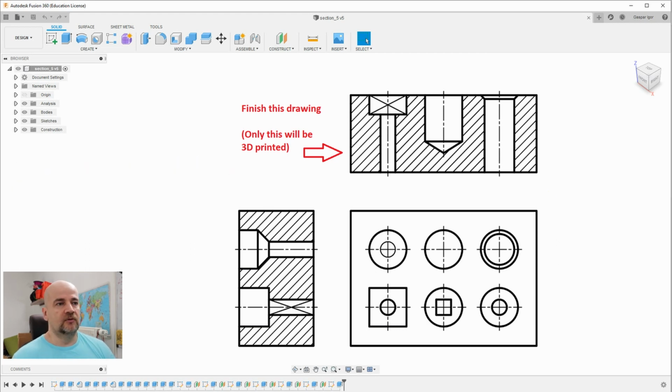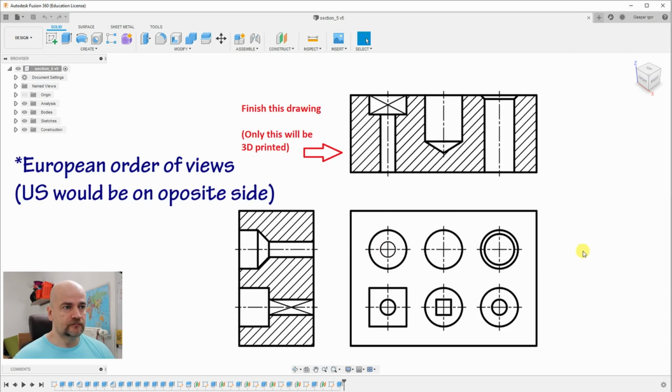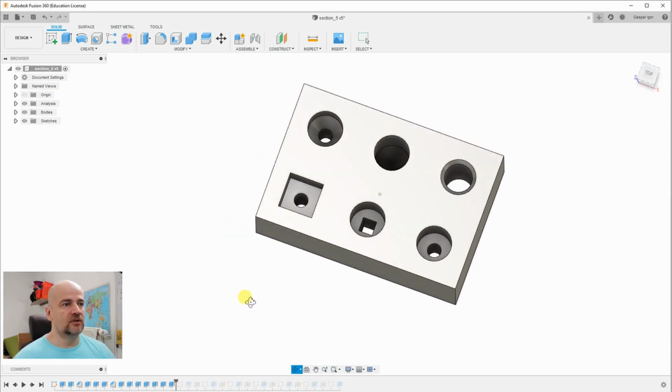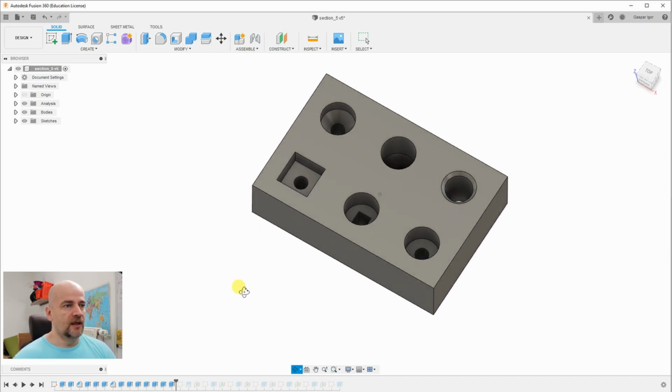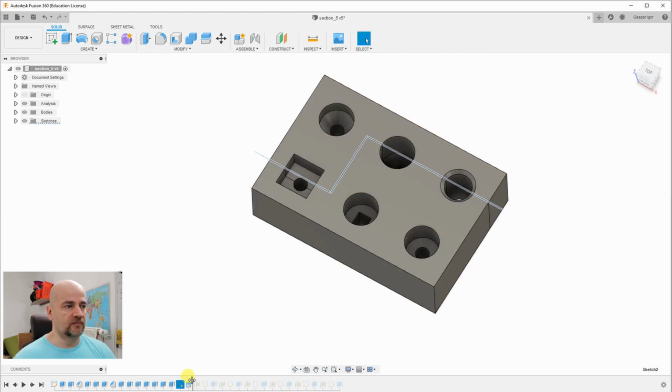But for example, if those holes are not aligned, like in this drawing, then it makes sense, because we can show the inside of these parts in only one view. Here I'm designing a 3D printing object only to show the upper section view. This is a three-dimensional object. I drew those holes which are on that drawing. And now we have to do cutting here and here. So I draw these lines again in this plane, and I use them as a base for the split tool.